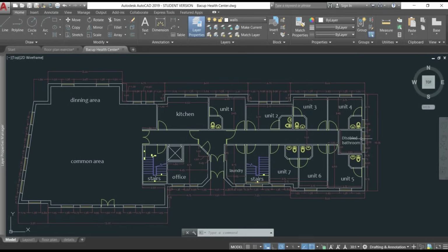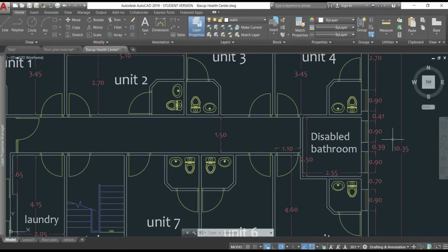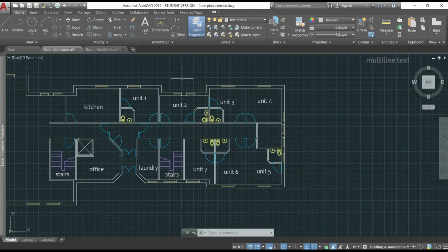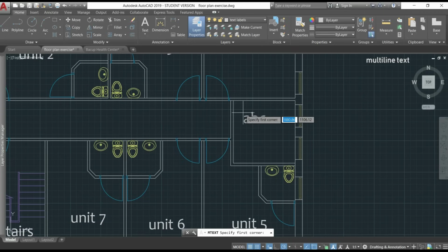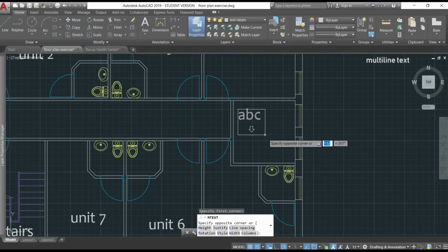Before going ahead in this tutorial, I want to mention this label, which has two lines. We are going to make this with a multiline text. As you remember, I can go to the arrow under text, and there is the option multiline text. To activate this command using the keyboard, you can simply type T. This is a bit different, as I have to open an area where the text will fit in this box.